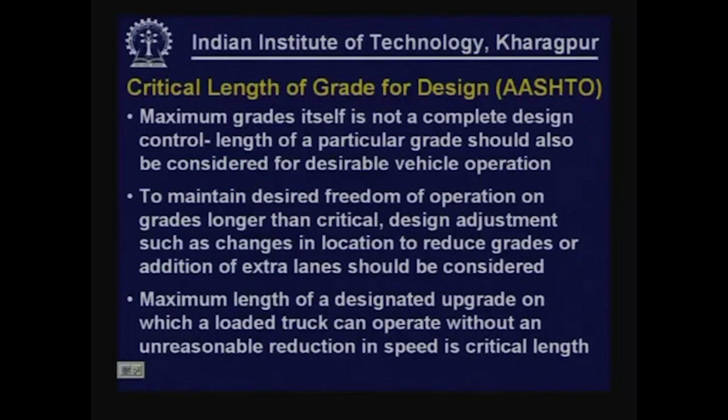Now, let us try to formally define what is critical length of grade. We have already discussed it, but let us try to define it now. Maximum length of a designated grade on which a loaded truck can operate without an unreasonable reduction in speed is critical length.